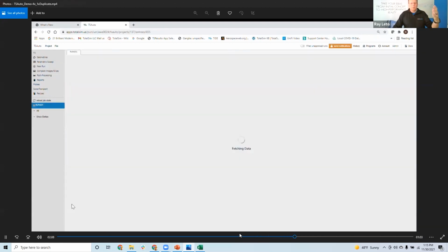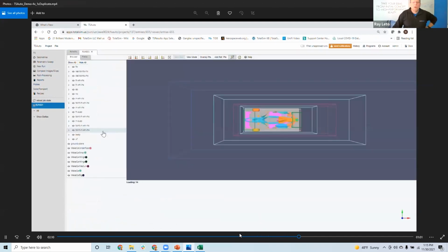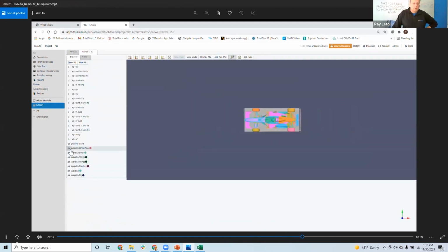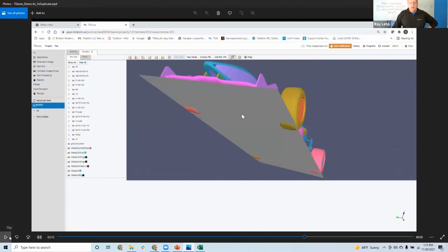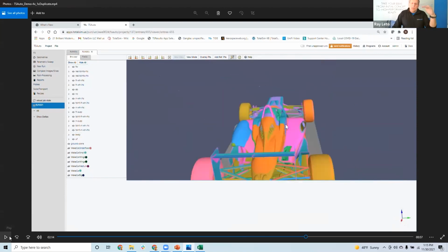So that's why typically when we talk about mapping, we're talking about what it's like in relation to the ground or the air. And especially with a formula car like we have demoed here, that ground clearance is critical and changes the aerodynamic performance hugely. So we have to be very conscious of it. And we're talking down to the millimeter type accuracy here.